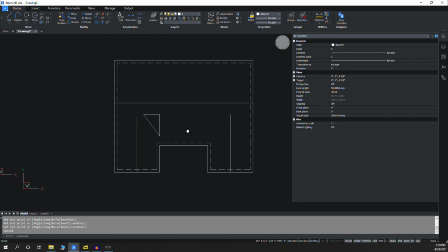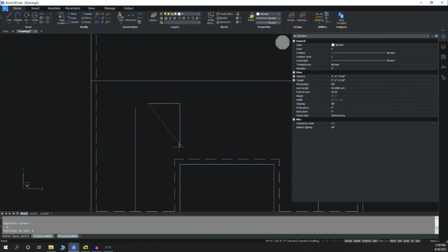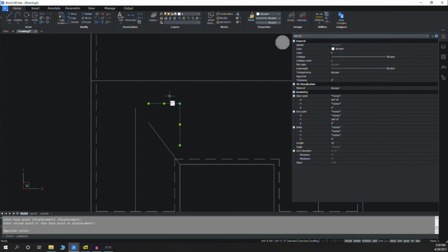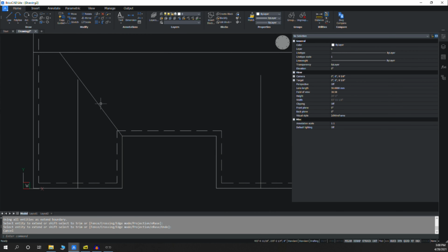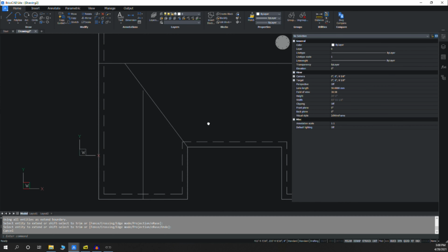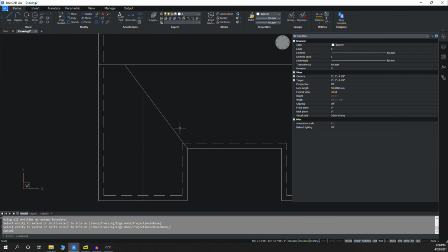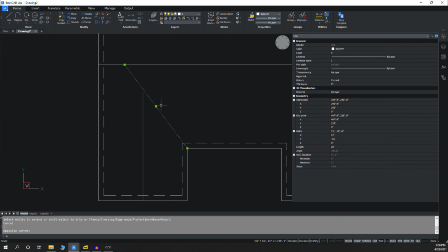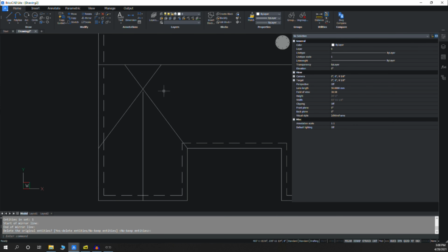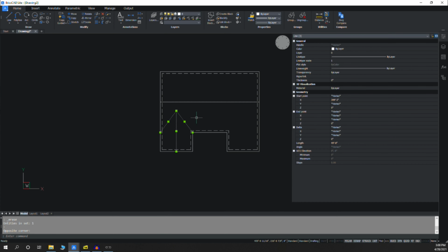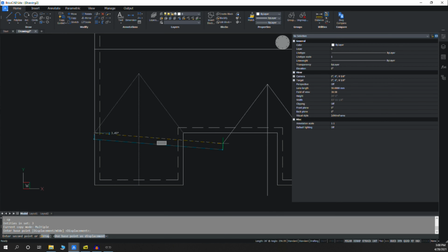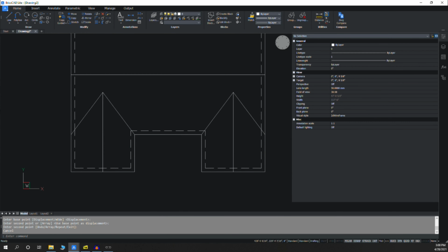And now I've got this angle, and it looks funky. It's not 45 degrees. Figuring this out with trigonometry would be really painful. Trust me, I've tried. But now we have the valley for how this kind of strange gable intersects with the main roof. Same techniques as usual. I just mirror across the ridge line. I actually have to extend this ridge line because it wasn't long enough. Then I can trim it. I don't think there's any reason to save that. I'm just going to copy this across, because both of my gables happen to be the right size.